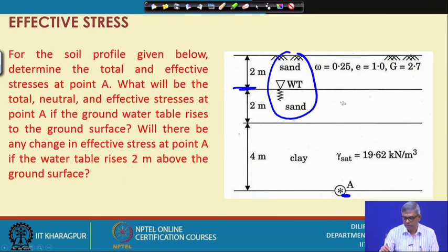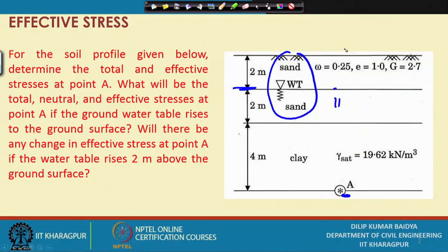Below the water table, soil is always saturated, and above the water table it can have three different situations. It can be dry, it can be partially saturated, it can also be saturated without a water table. How will this saturate without a water table? Generally, as I have mentioned, soil has very fine particles, and through the interconnected void spaces, the water can flow, and that is capillary action.